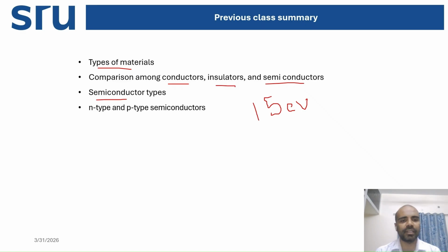An intrinsic semiconductor is a pure form of semiconducting material. It is an extremely pure semiconductor, containing no impurity or no doping. But in case of extrinsic semiconductors, a certain amount of doping or impurities is present. There are two types of impurities: donor impurities and acceptor impurities, or you can say pentavalent impurities and trivalent impurities.